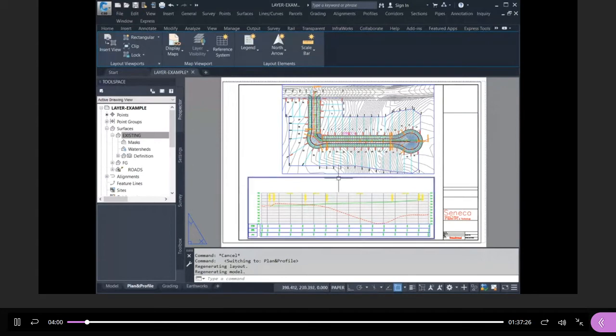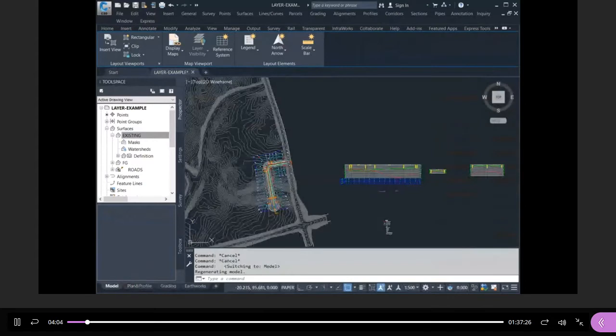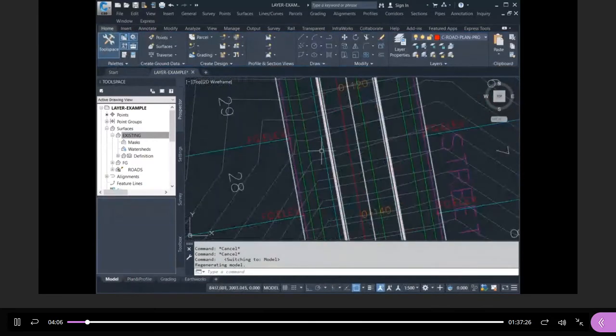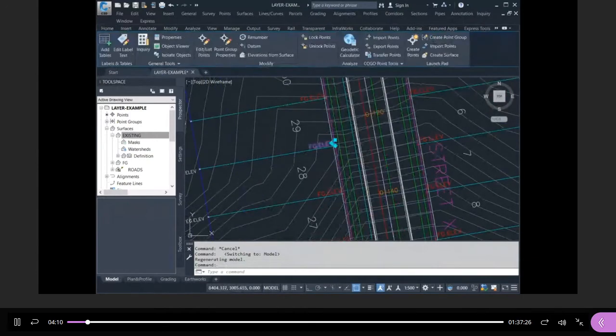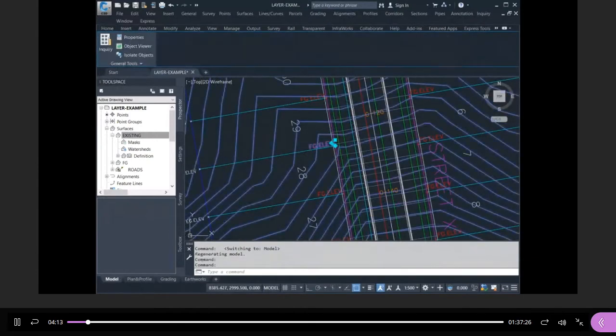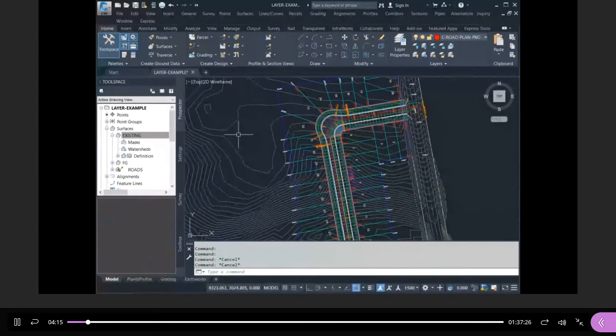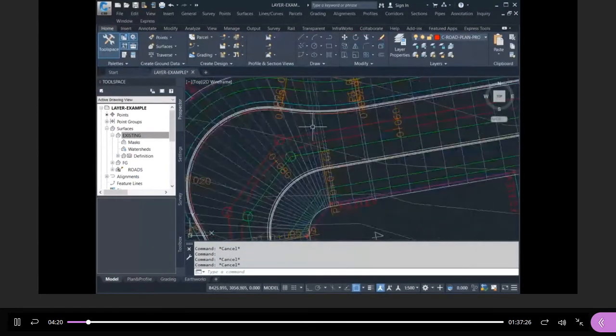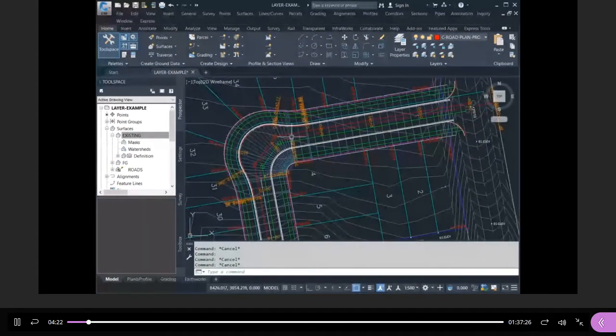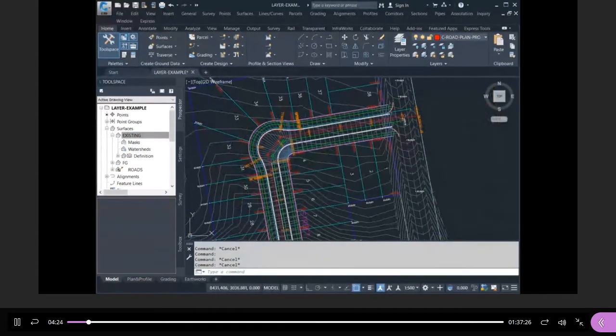So the way I've got it set up now is everything in the viewport is visible based on what's in model space. So in model space, we have everything. We have the grading design, and it's not complete yet, right? But we have an elevation at the front, an elevation at the back. So that's the grading information. We have the existing ground information. That's the surface. We have the maintenance holes. We have the pipes, right? And we're not done with the pipes yet, but when we are, you'll see all the pipe information as well. The length, the slope, the material, the size. We'll get into all that. Okay? The water main is showing and so on.